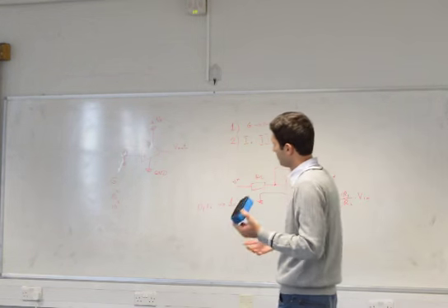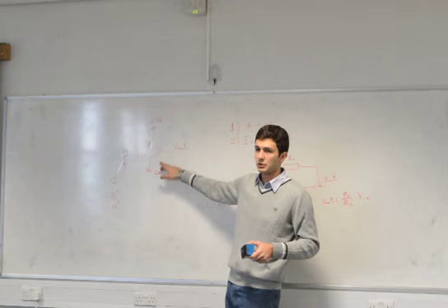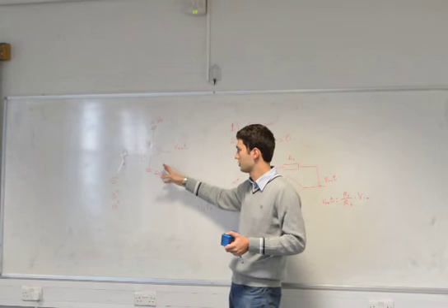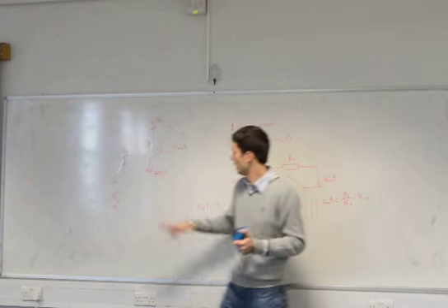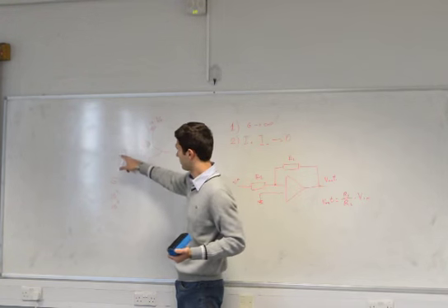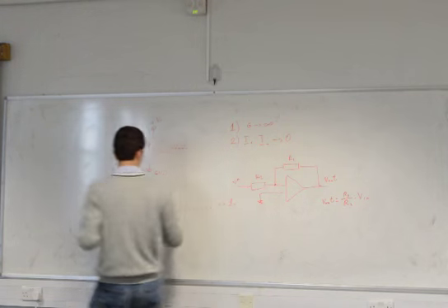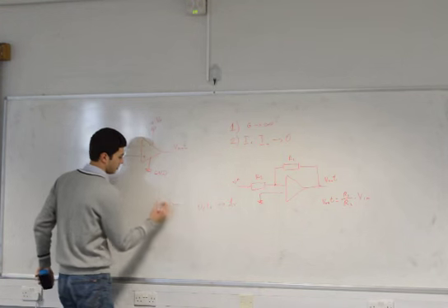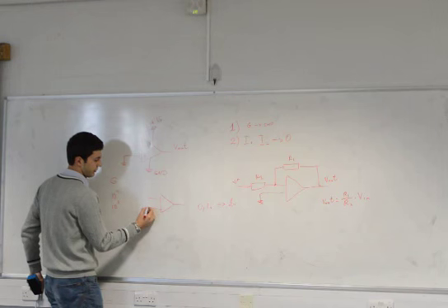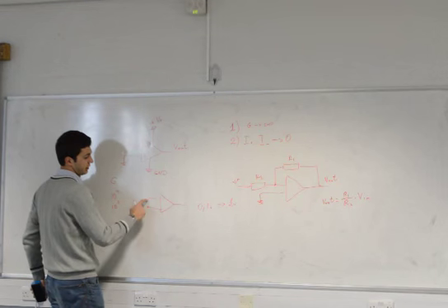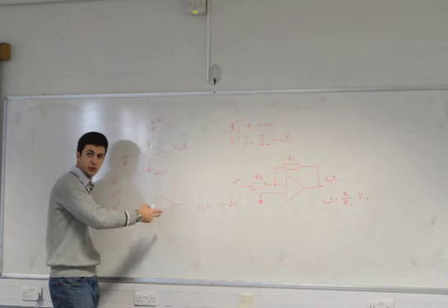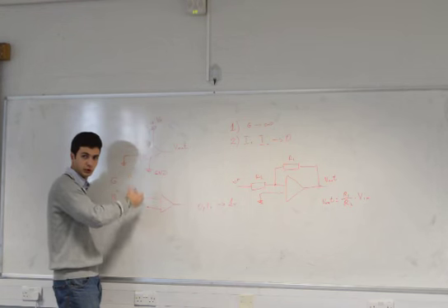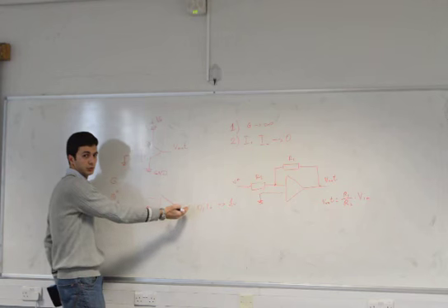etc. When we drew this yesterday on the board, we drew this in the regime of comparator, not an operational amplifier. So what we did, we just put a reference voltage here. So what it does, if we have a voltage of some kind here and then another one here, the difference will be multiplied by the gain, and if one is more than the other, we will have positive output.